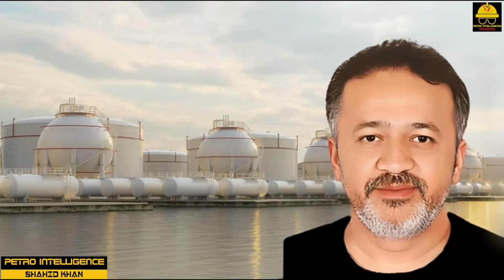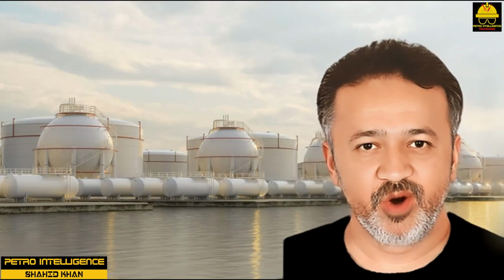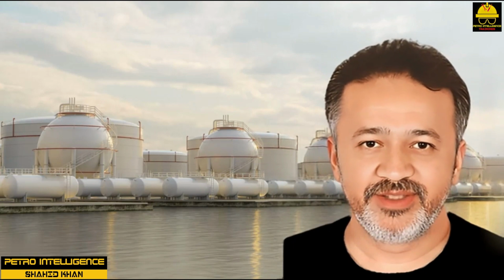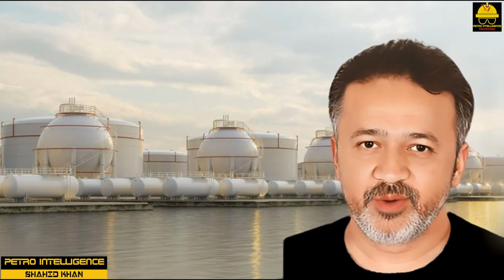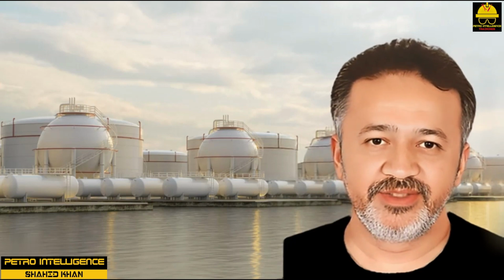High alloy steels. The properties of steel can be varied widely by small additions of other elements to produce steels that are satisfactory for most services. In some cases, however, it is not possible to produce steel that is satisfactory for a particular service by adding small amounts of other elements, and larger quantities of alloying elements are necessary to produce the desired characteristics. Steels that contain 10% or more of alloying metals are generally called high-alloy steels. The members of this group most often used in plants are chromium steel and austenitic steel, that is, stainless.